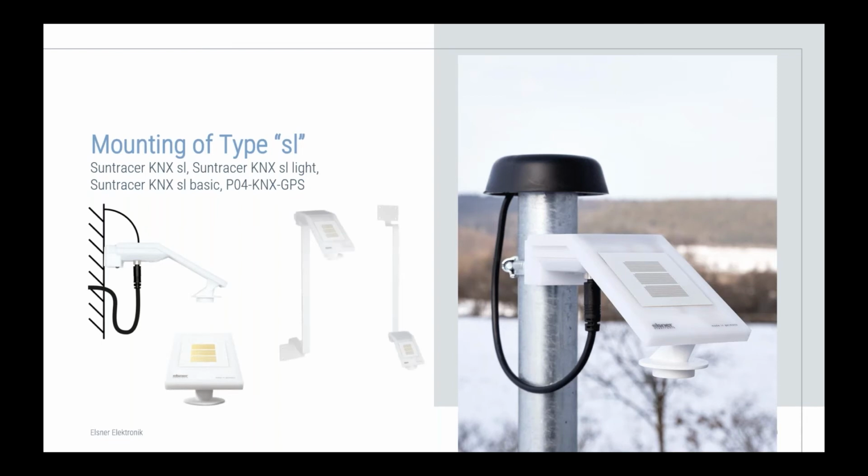Here you can see the boom. So this is also very important that you have a lot of space below the weather station so the wind measurement can measure correctly, because if there's not at least 60 centimeters below the weather station, the wind sensor can't measure correctly. Sounds pretty easy, but it's actually one of the most common mistakes that we encounter in our service department.